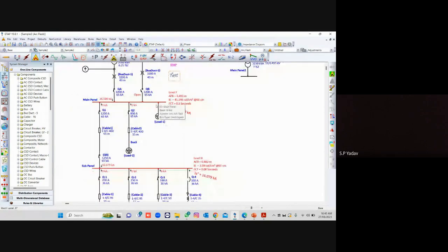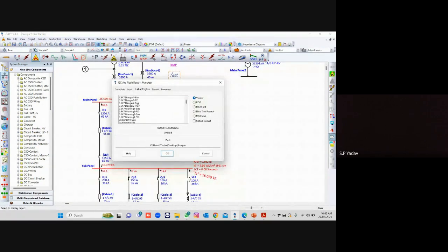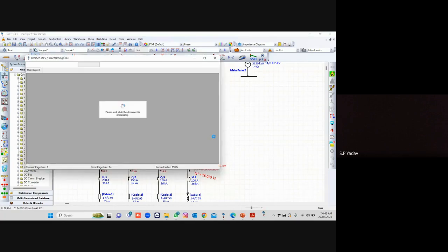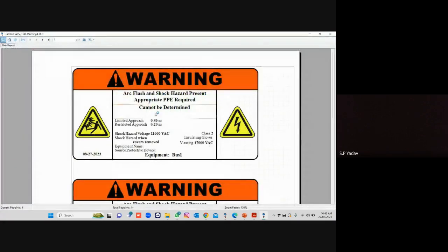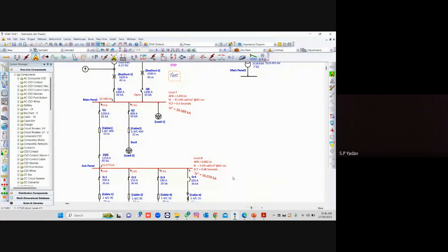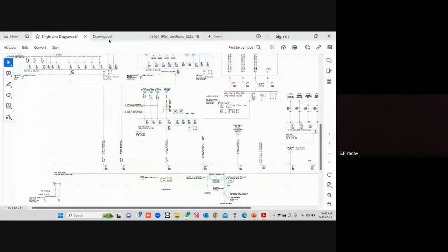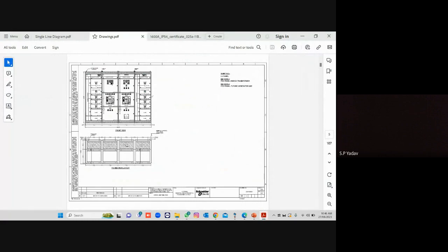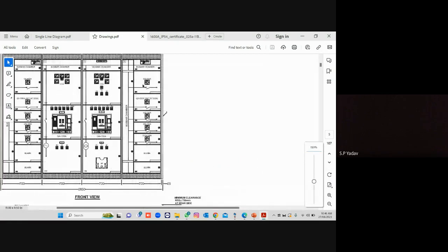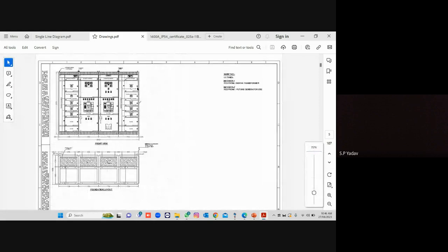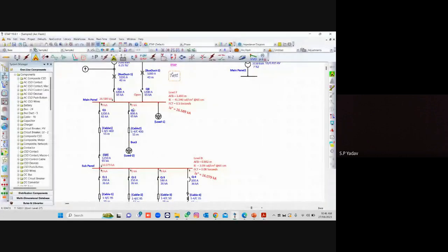This is a somewhat vast subject. We can create the labels also here for arc flash analysis. How do we need to enter the data? For that, we have to understand these drawings: how the electrode configuration is arranged, which compartment it is, what the height, width, and depth of the compartments are, in which area the protective device is located, how we need to enter these details, and what the manufacturers are. We can manage those inside this bus editor.